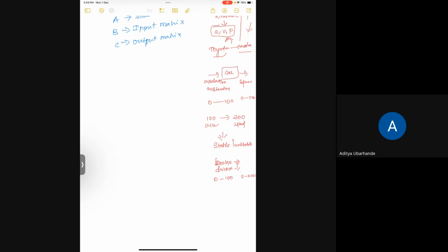Do you understand? Okay, so as far as I understand it, when we have multiple things contributing to some output, like in this case, the accelerator is the main input, which is converted into speed of the car. But there are other factors, like you said, tire friction or some air resistance or something. So in those cases, we are supposed to use this variable thing. In those cases, you will get more accurate information about your system so that you can do more accurate control when you design a control.